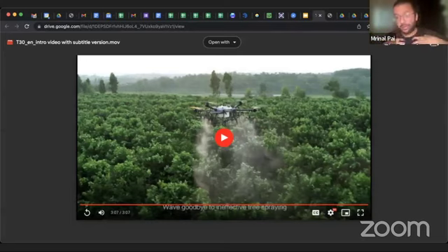These drones, compared to manual methods, which is the commercial part of it, what is happening today, for example, spraying rice with either pesticide or herbicide: for a given labor, it takes one person close to 1 day to complete an acre. And it would require close to 150 to 200 liters of water to spray. And that's the practice today.